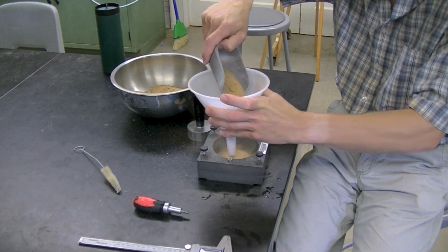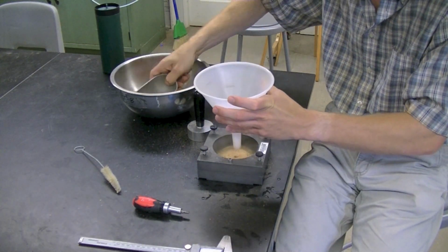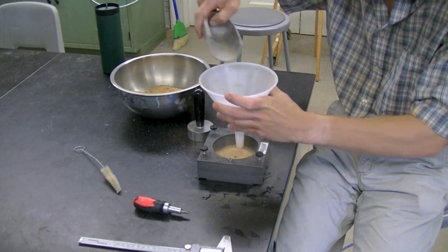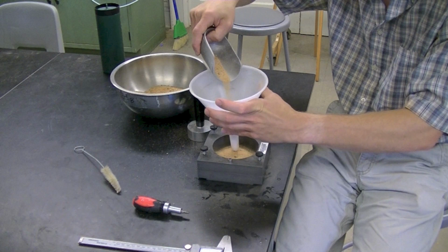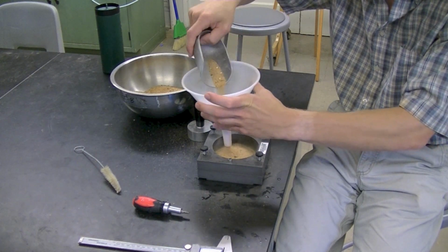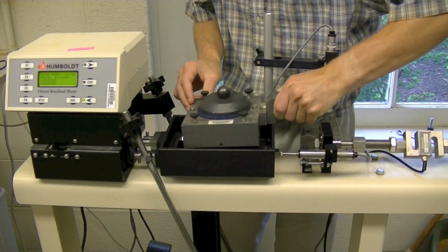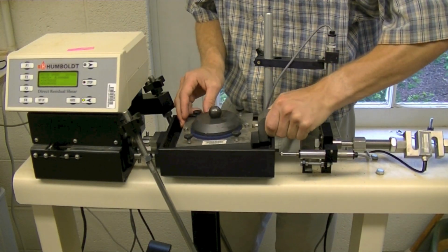After cleaning the shear box thoroughly, repeat the molding process. Be consistent and mold the sample in the same manner as the previous run. Take mass measurements and moisture content determinations as needed, ensuring similar relative densities.